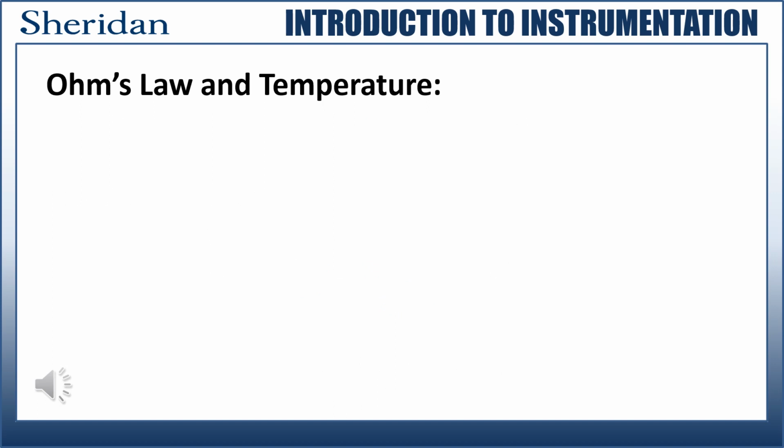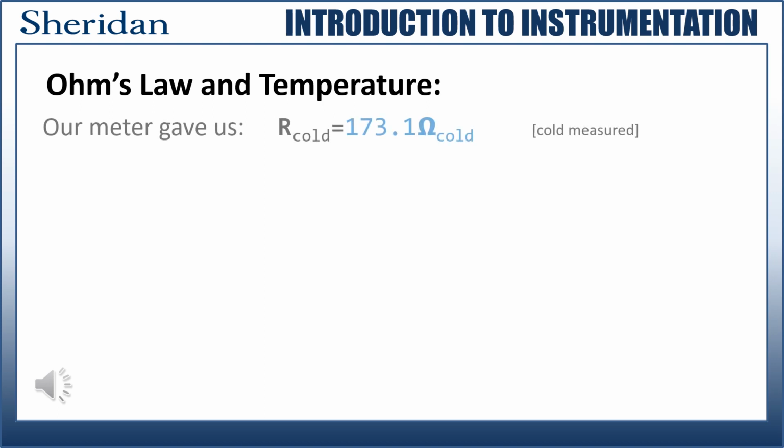Okay, let's start again. Our meter gave us a cold resistance of 173.1 ohms. It also gave us 101 milliamps. It's a good tester, and the batteries are fresh, so it isn't likely the meter. Okay, maybe we should try something different. I mean, Ohm's law is a law, and that means it should always work.